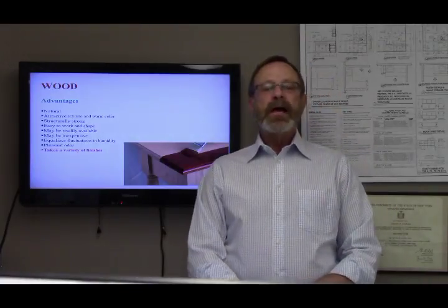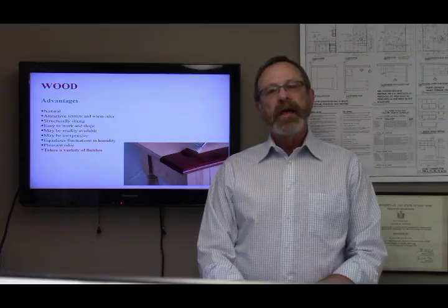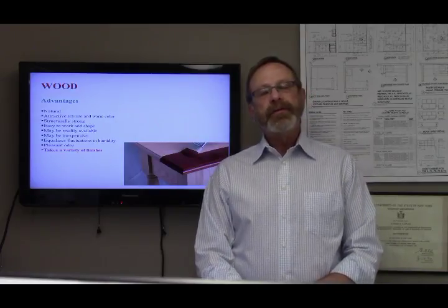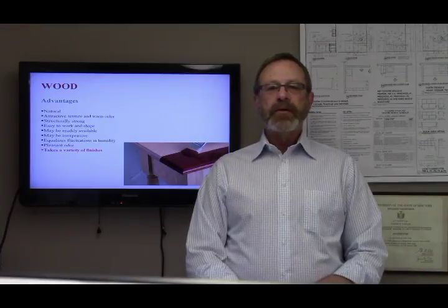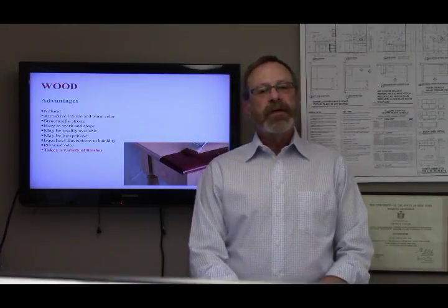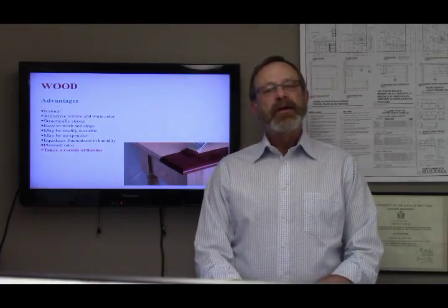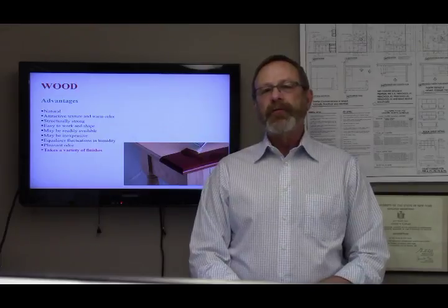Finish is used on woodwork to protect it from moisture, chemicals, and contact, and to enhance its appearance. Woodwork can either be field finished or factory finished. Because more control can be achieved with a factory finish, it is the preferred method, though minor cabinet and trim work is often field finished.